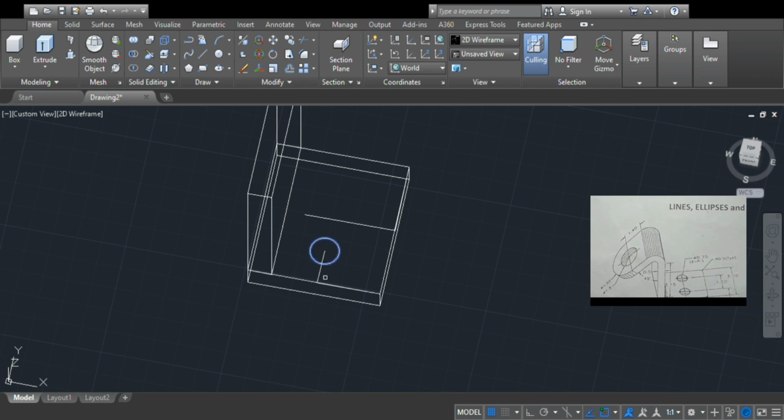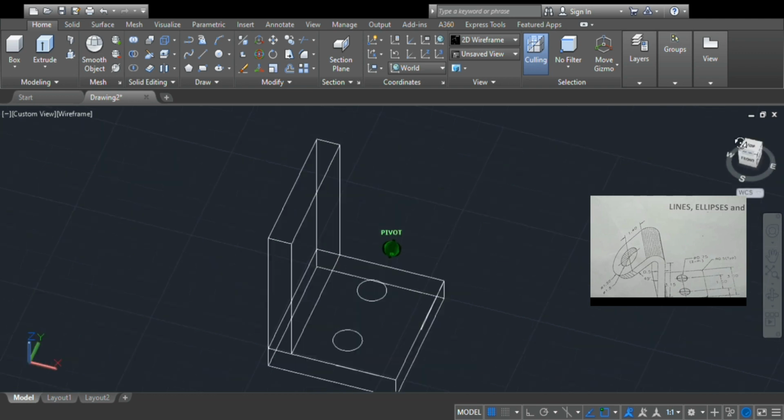So I have to select this circle and the initial point I measured to get that point there. And I will tick here as my midpoint, so you can see that object has been mirrored over there. All you have to do is click the mirror tool, click the object first. Okay, now it's mirrored there. Enter. Now I can delete this midpoint I used for reference, and also I can delete these lines. They're not needed. I just need the circle there, but I used those points as measurements.